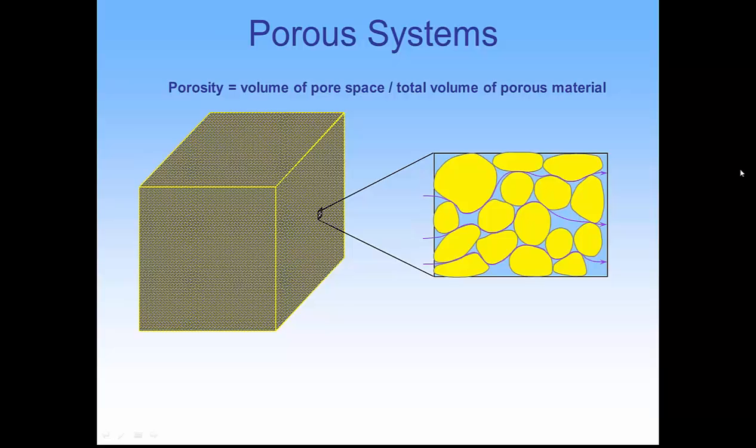So if I had a glass of sand and maybe the porosity is about 30%, that means the void space or the air space in that glass is 30% of the total volume. In an aquifer, that's full of water. So the best way to describe that is if you have an aquifer that's 100 feet thick and it's a sand and gravel aquifer with a porosity of 30%, then there's about 30 feet of water there if you took all the sand away.